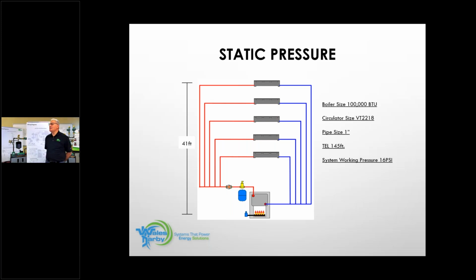So while they're doing that, let's discuss that green line. ECM circulators have to hit a certain efficiency. Originally, when they launched the 007s, if it had a demand for more than 24 hours, it had to adhere to a specific energy level. So it wouldn't be orange anymore, it would turn green, and it would run that green line curve to reduce the power. This mostly happened in Massachusetts.